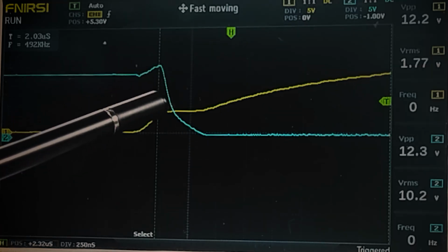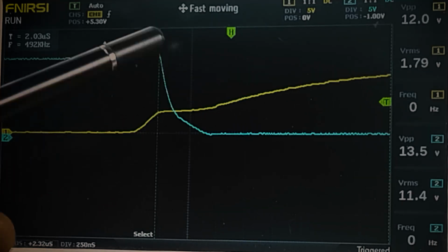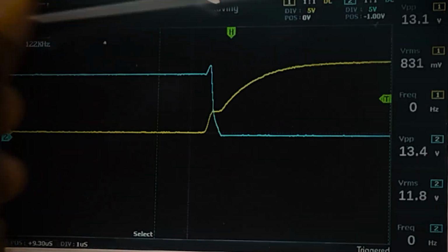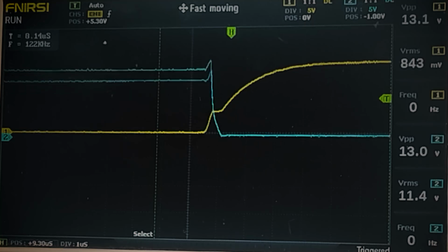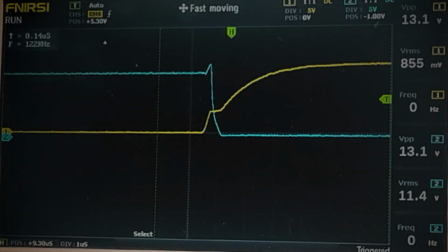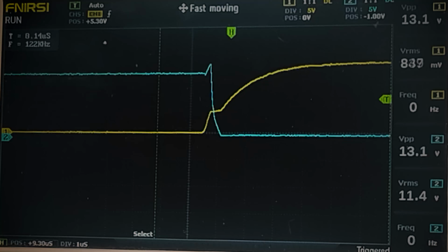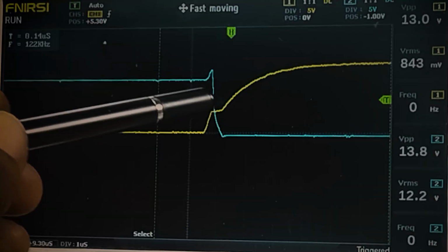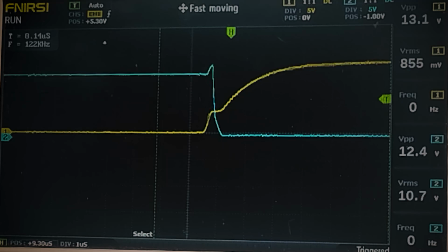If you look at the wave, you will see that after our drain-to-source voltage drops very low, our gate-to-source voltage continues rising. So we see that steady rise to the top right up until the MOSFET is fully on. The same thing happens during switch off, and this is what is called the Miller plateau. Now why is all this important? The Miller plateau happens to be the slowest part of the switching period, and during this plateau we have a resistance between the drain and our source, therefore a voltage drop, which equates to conduction losses.